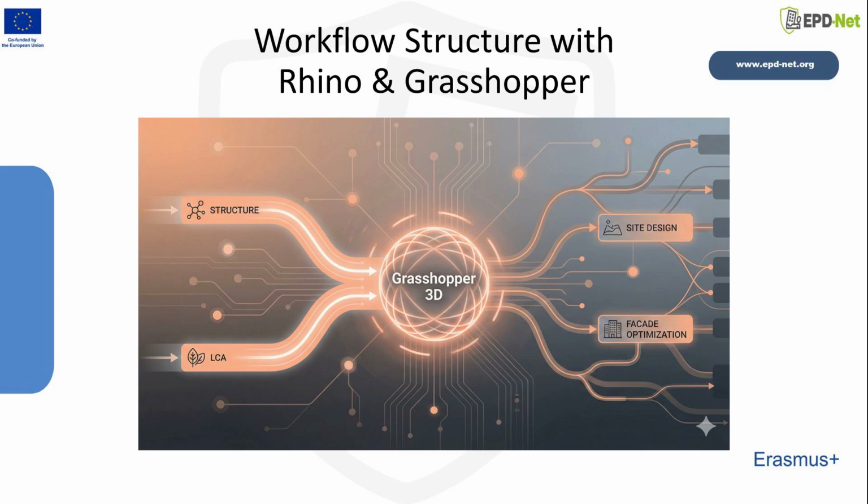Parametric design also enhances climate-adaptive site planning. Rule-based evaluation allows building codes and environmental standards to be encoded into digital tools, while hydrological calculations for rainwater detention ponds can be fully parametrized, including catchment areas, runoff coefficients, rainfall durations, and required detention volumes. This supports accurate stormwater management and reduces flood risk. Additionally, parametric optimization supports passive design strategies such as shading, orientation, ventilation, and daylighting, enabling designers to explore geometric adjustments that respond effectively to site-specific climatic conditions.